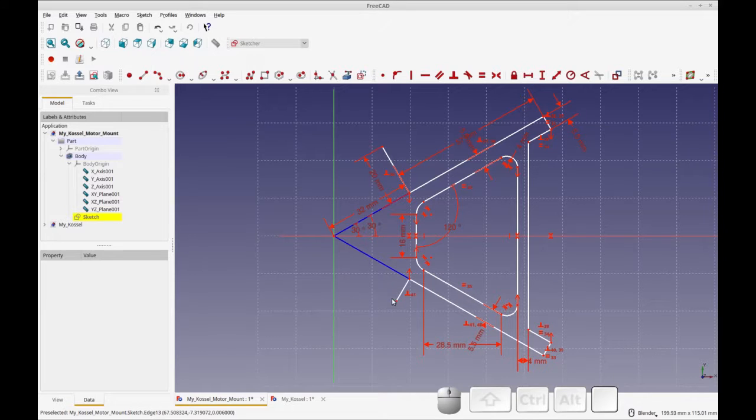So the final thing we're going to be doing is adding this front curve. So the front curve is going to be added using the arc tool. Let me just highlight this so we can see, create an arc. And we're going to be using the two endpoints and rim, sorry, midpoint. And the endpoints we're going to use are the ends of these extrusion stops. So I'm going to go from that extrusion stop to this extrusion stop. And then I'm going to coincident on this construction geometry. Now you know why that construction geometry is there.